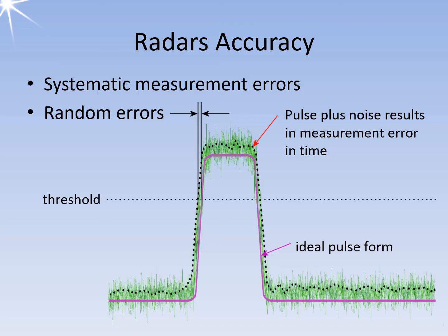The accuracy of the angle measurement depends both on internal signal processing methods and on external conditions. Anomalous propagation conditions, which frequently occur due to changes in air pressure in height angle measurements, can principally also occur in bearing angles and form a random error. However, more frequent systematic error sources have internal causes.